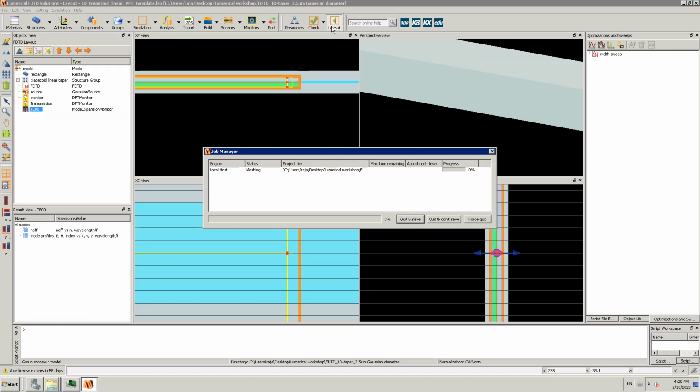Because the problem is that you already gave auto, it will give you like 3 hours initially, but then you also gave an auto shut off level. So maybe in between these 3 hours you reach the auto shut off level and the simulation will be closed. So it's difficult to predict the simulation time. For me it's 23 minutes. For you guys it will be much more because I'm using a simulation computer that has a lot of cores, so everything runs in parallel. I will most probably be using more than 70 cores at a single time. For you it will be much more than this.